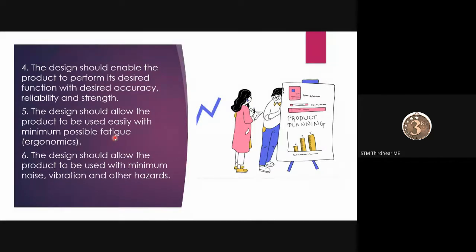But in modern-day vehicles, there are power assisted systems, power steering, power hydraulic type gear lever systems, etc. Many technical terms, but the major function is that it eases the fatigue, as we have to provide only a small load to achieve that function. The function is to turn the vehicle. With power steering, you just have to give a small turn of the steering wheel to achieve the maximum turn in the vehicle.